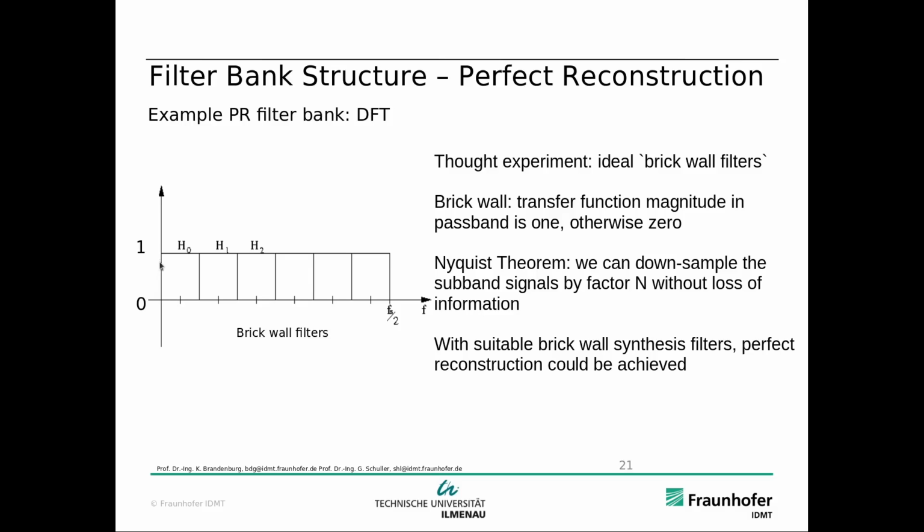And you can see here this low pass filter directly touches the next bandpass filter, but they don't overlap, right? And there's also no gap. So this is really ideal. It's called brick wall filter because this looks like a brick wall. So theoretically that's quite nice, but unfortunately you cannot realize it. So that's more for theory.